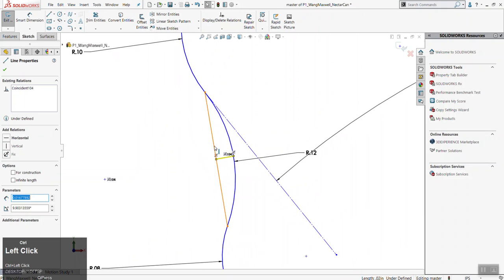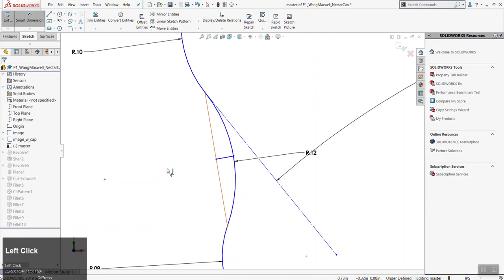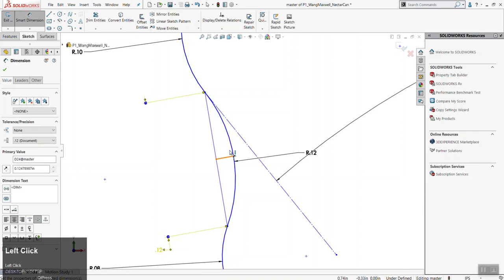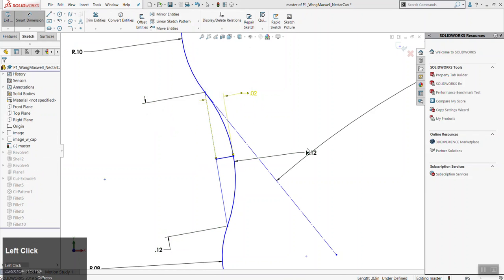There's a lot going on here. It will happen sometimes. So if you give these two a perpendicular relationship and then define this and this, obviously these should be for construction. This is another solution on how to define an arc in a different way. It's overdefined now because of this guy right here.